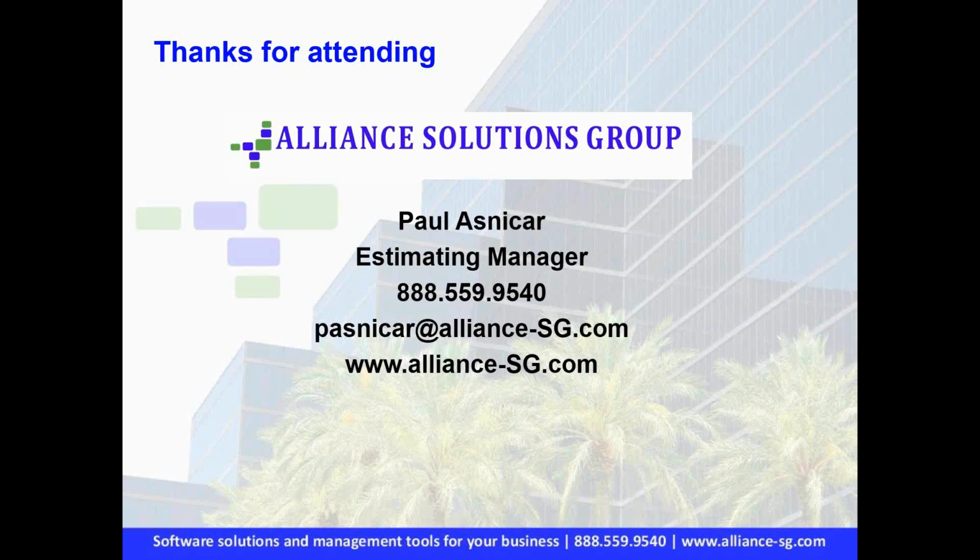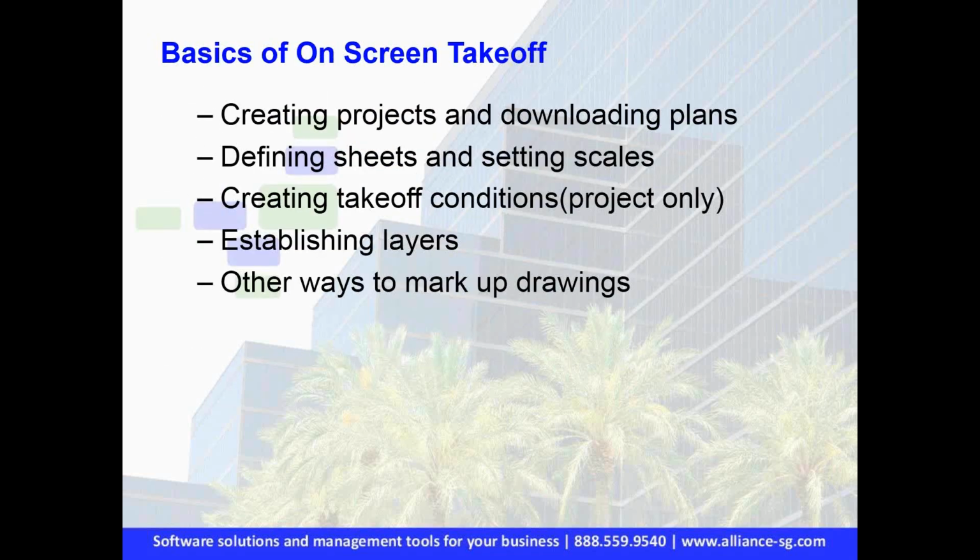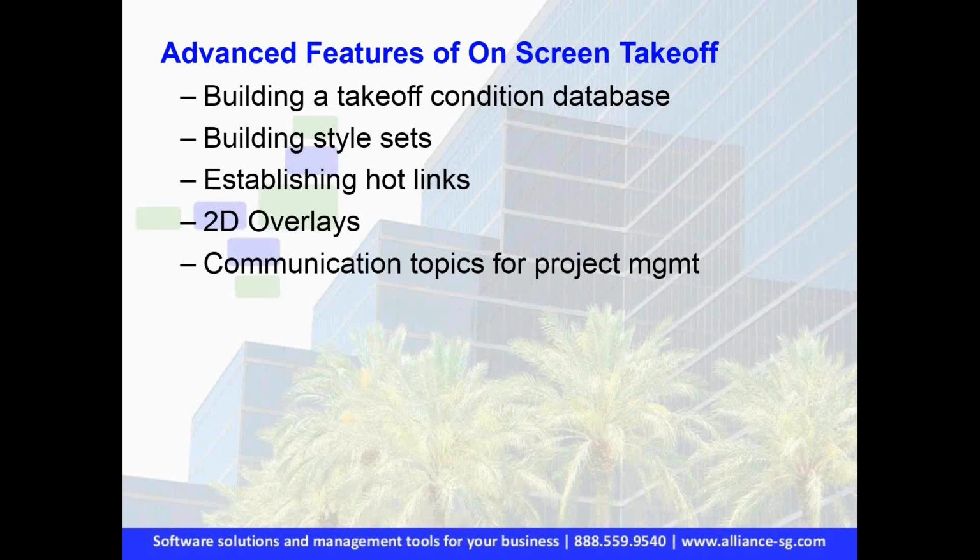So if I come back to this here, the reason I've broken this into chunks is that a lot of it is how I implement on-screen takeoff. The nice thing about on-screen takeoff is, once you do the install, you're downloading a set of PDF drawings as an example, and then, once you set some scales and start working with it, you can use it kind of out of the box.